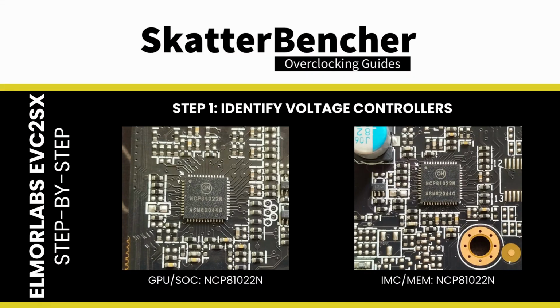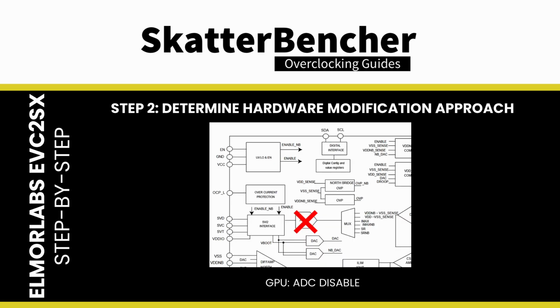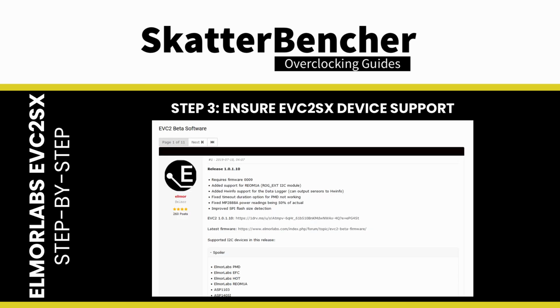Step 1. Identify the voltage controllers you want to control with the EVC2SX. We did this in the previous segment. Step 2. Determine how the hardware modification will work. And we also did this in the previous segment. Step 3. Ensure the EVC2SX supports the I2C device. You can refer to the EVC2 beta software forum topic for a complete list of the supported I2C devices. If your device is not listed, you can leave a message in the forum or Discord.